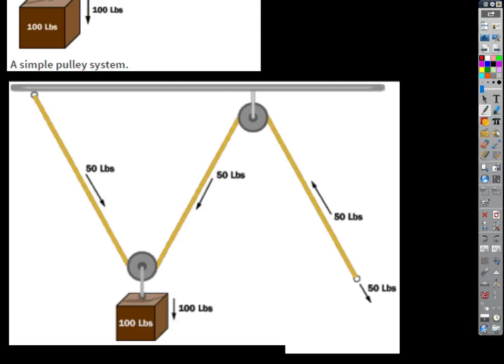What's wrong with that one? Can you tell me something else? The angle's not vertical. Yeah, right. And so remember when we talked about icicles breaking power lines? As that angle gets closer to 0, it gets more and more inefficient, because only the vertical component of the tension is supporting the load. There's some wasted horizontal component there.